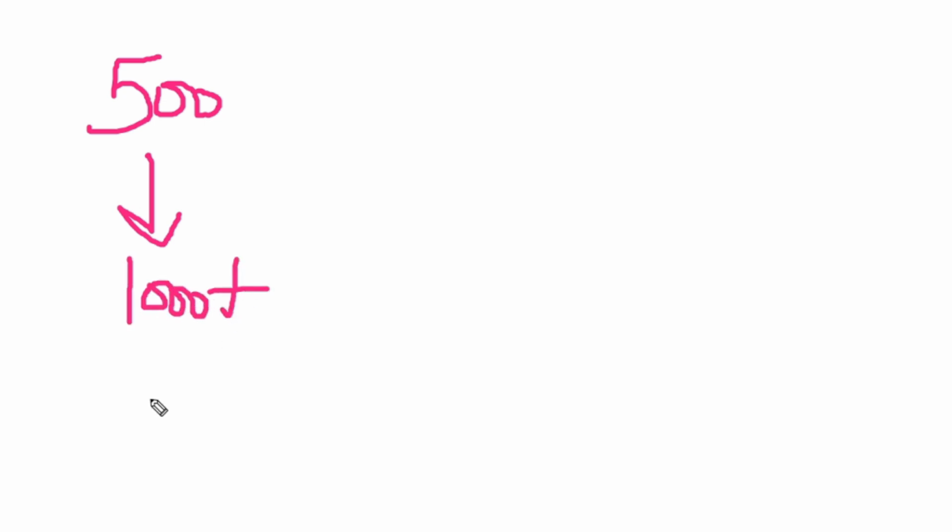First, you get a value of 500 on a reverse bias, and when you reverse the probes, black on a ground and red on the testing point, you get nothing or a 1000 plus reading. That means it's an OK sign from here. That doesn't mean there is no problem on the circuit.